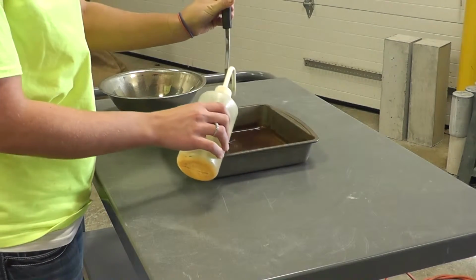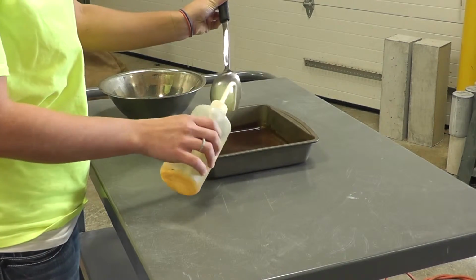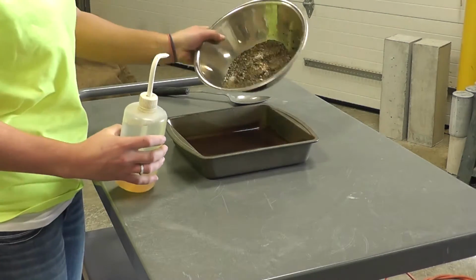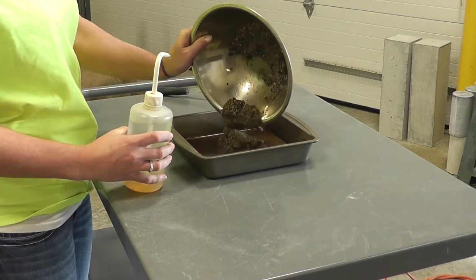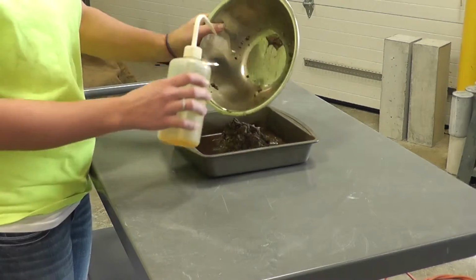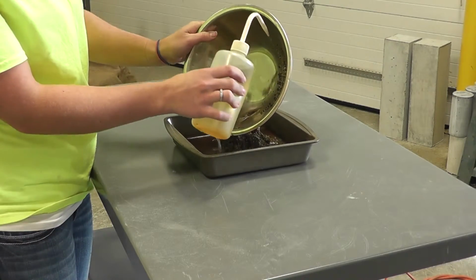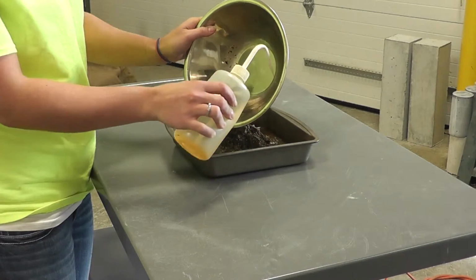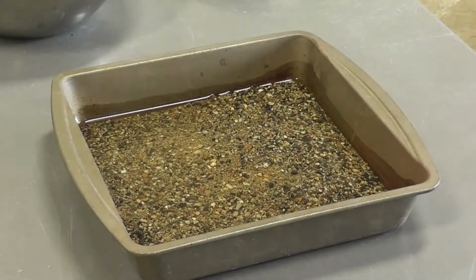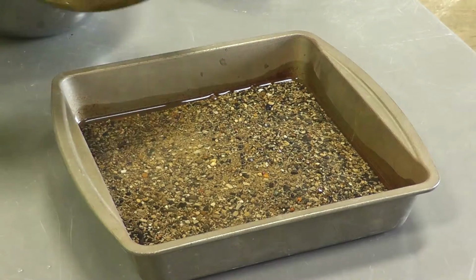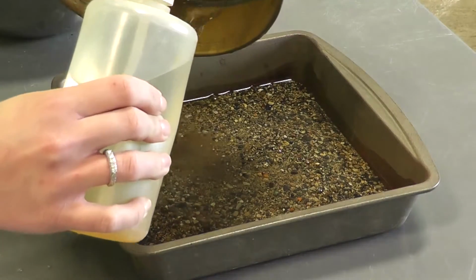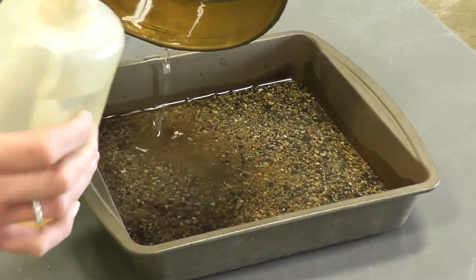Next, the sample needs to be put back into a pan for drying. First, materials in the agitating container and spoon are required to be transferred into the drying pan. The agitating container is then rinsed out, being careful to not lose any of the fines. A rinsing bottle may be helpful during this stage of the process. Then the material retained on the sieves is transferred to the drying pan. Again, a rinsing bottle will be helpful in removing all of the fines in the sieves.